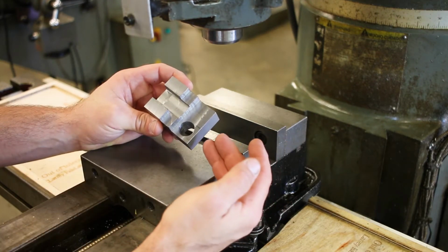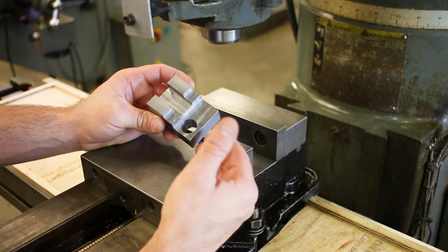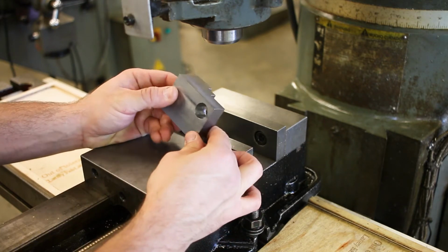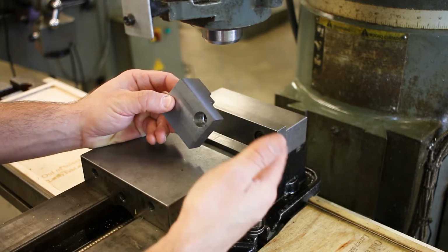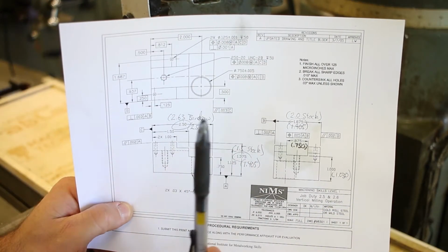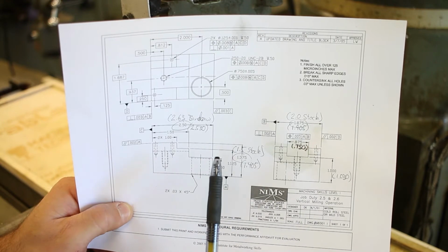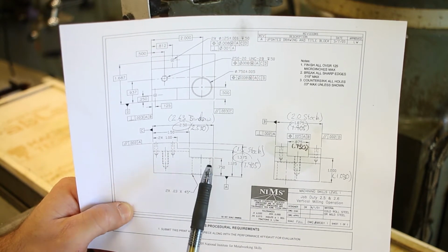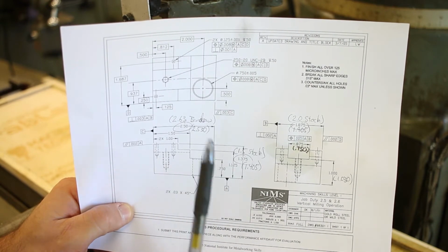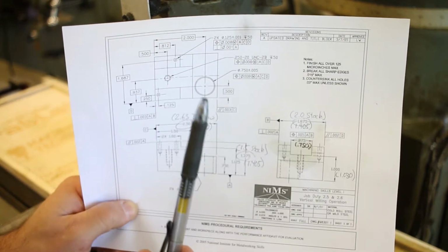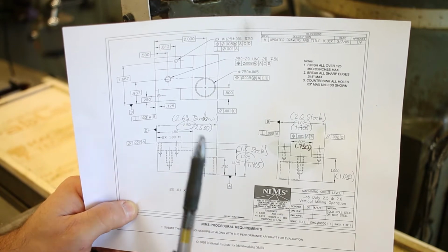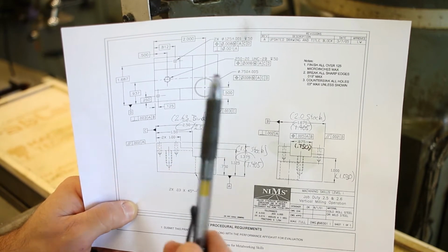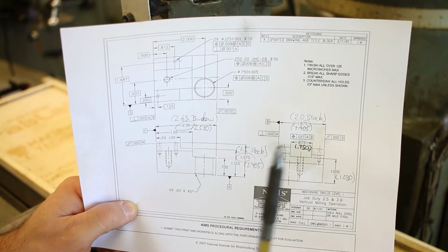Whenever we're machining a part, we always have to ask ourselves, what is the appropriate sequence of operations? Which surfaces should be finished first, second, third, etc. Now, the print doesn't tell us how to machine the part. That is the prerogative of the machinist. But it does tell us what the final inspection criteria are. And those final inspection criteria very often specify a priority of surfaces, and that in turn suggests a sequence of